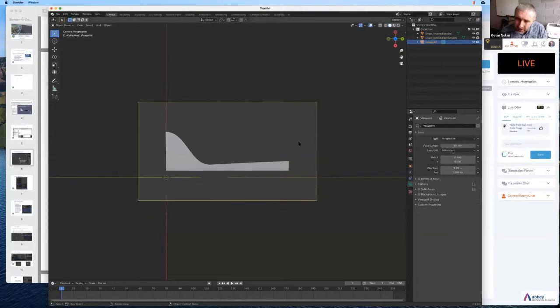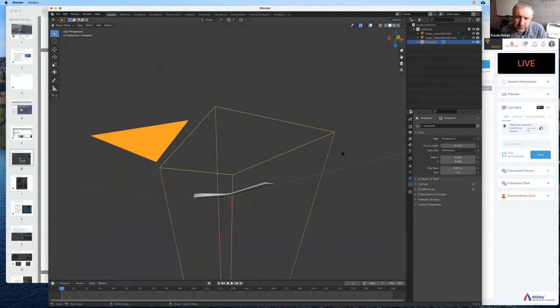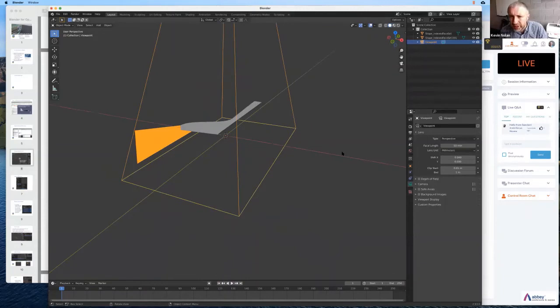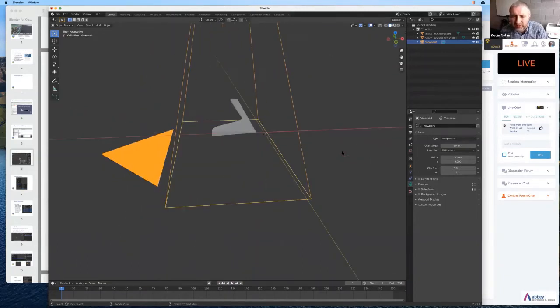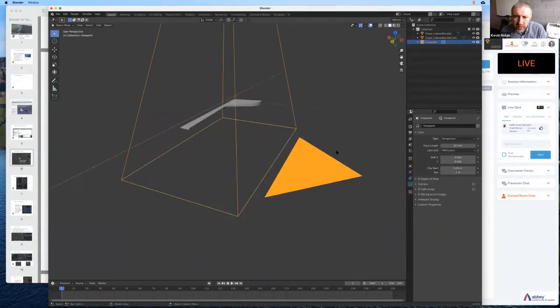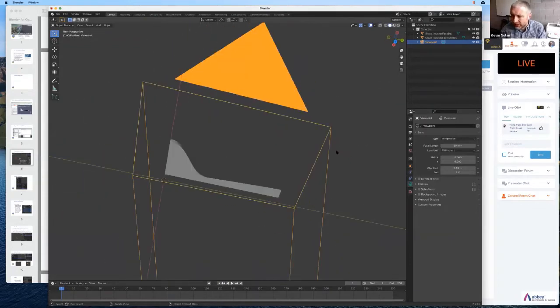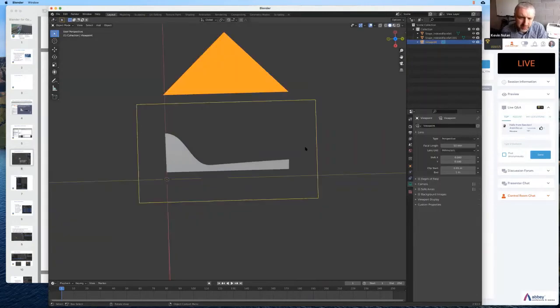Depending on what you import, it could be a very, very small geometry. It could be a very, very large geometry. If you're doing something with a geographical flow, maybe 1,000 meters is too big. So either you have to scale your model, or you just have to scale what the camera can and can't see. So obviously 1 meter here is plenty. Otherwise Blender is going to try and render all that, and it's going to struggle. So the idea is to cull geometry that's far away or too close, so you can still render, or so that very, very close geometry doesn't interfere with your renders. You can have objects passing in front of the camera that are unseen. So there are artistic reasons, I suppose, for doing this.